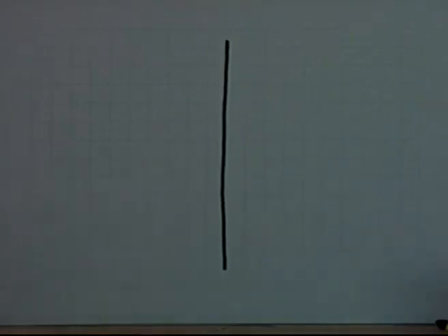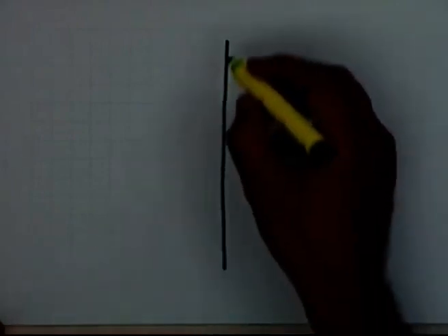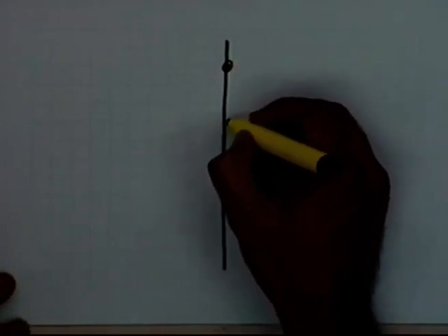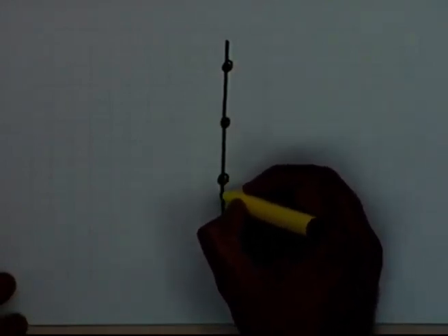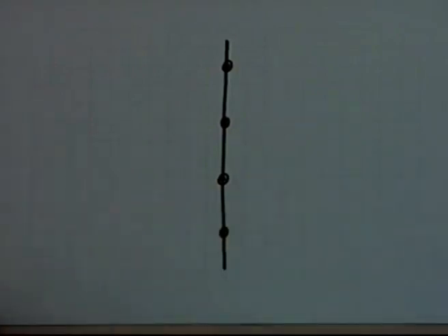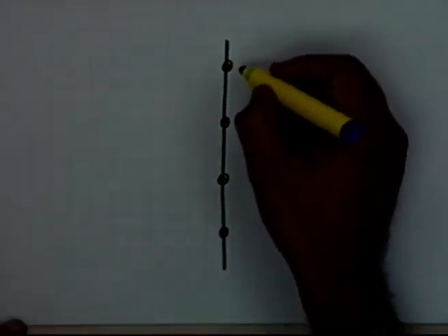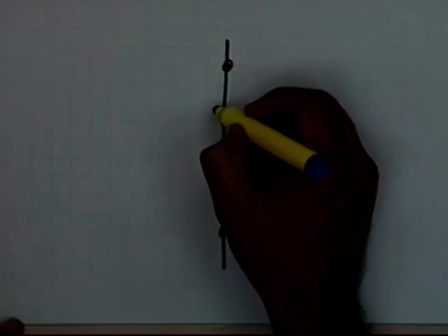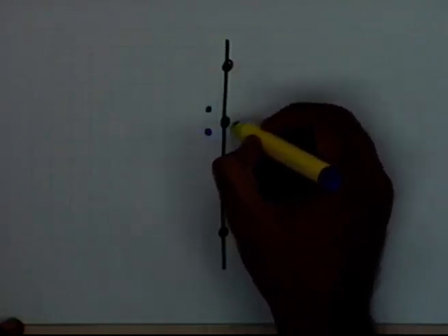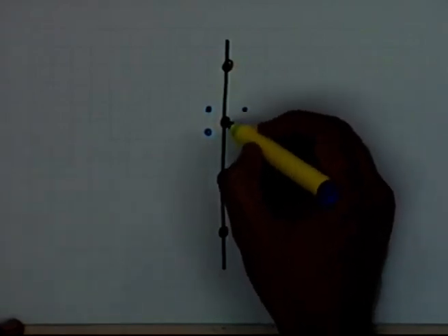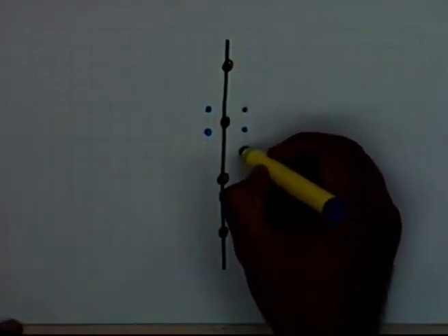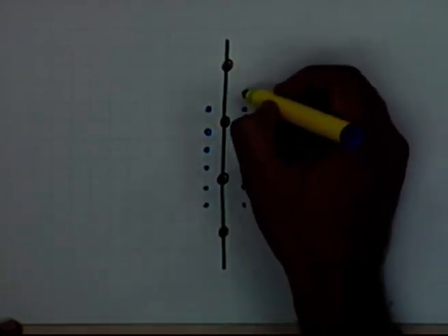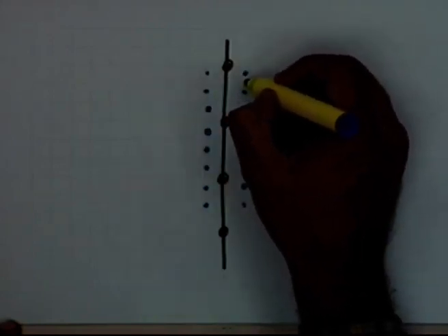You want to know what the uniformity coefficient will be, and if you have different sprinkler nozzles attached on the same lateral, your catch cans should be installed in such a way that the location of each sprinkler nozzle is somewhere in the middle of these catch cans. So now you can have the catch cans spread like this.